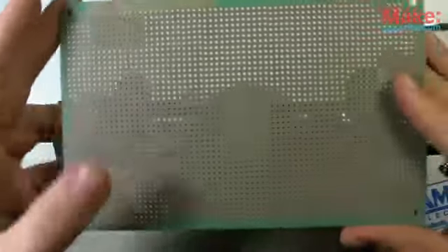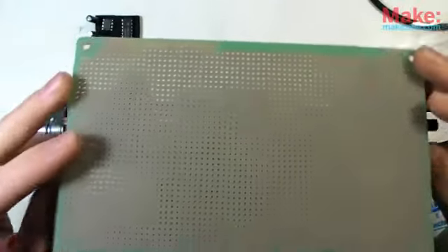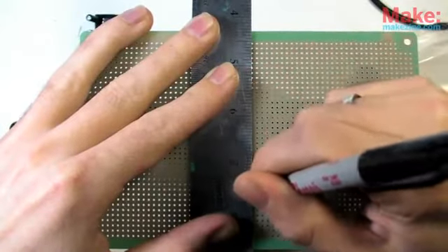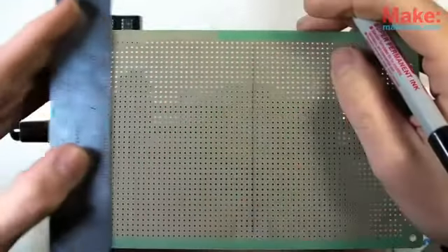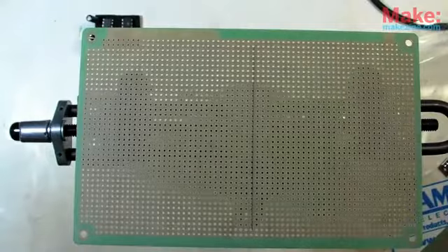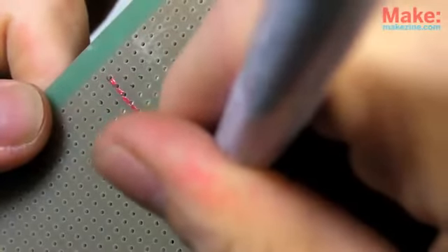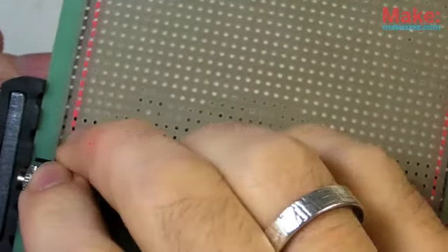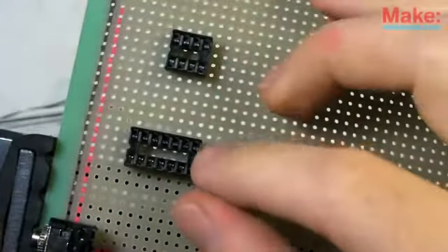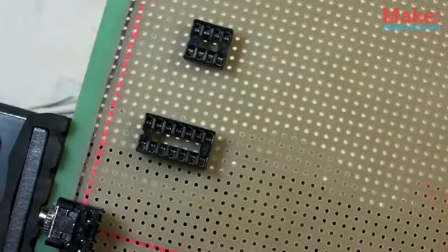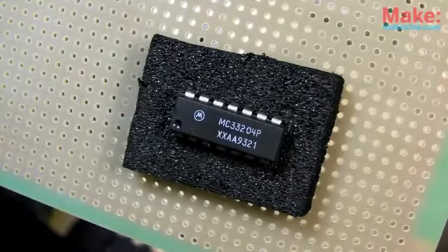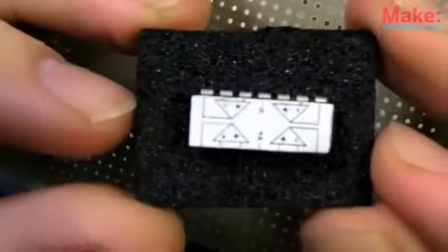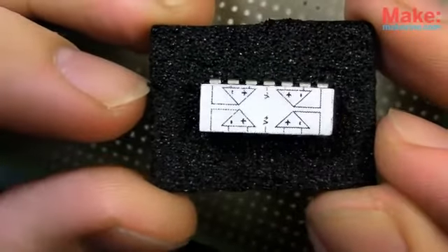To build it, I decided to use a rather large piece of perf board. If all goes well, I'll have space to duplicate the circuit and use them together as a 2-channel stereo color organ. I used a paint marker to show my power and ground buses on top. This makes it a bit easier to plan the initial layout. Having multiple op-amps on a single IC can get a little confusing, so I printed out a small label to keep track of each pin's connection.